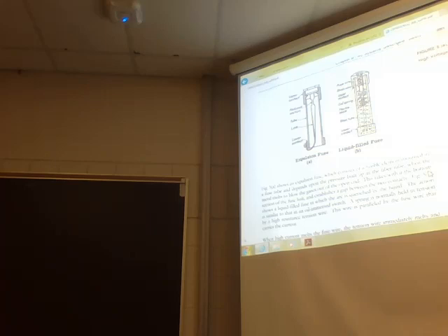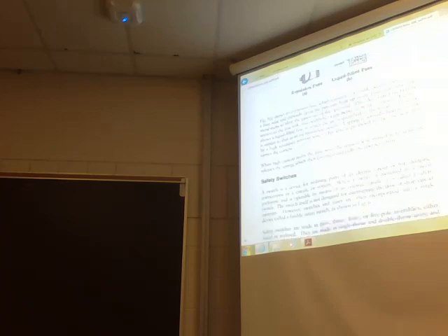Figure 5B on the right shows a liquid-filled fuse in which the arc is quenched by the liquid. The action is similar to that in an oil immersed switch. The spring is normally held in tension by a high-resistance tension wire. This wire is paralleled by the fuse wire that carries the current. When high current melts the fuse wire, the tension wire immediately melts and releases the spring, which then contracts and pulls the contacts apart.